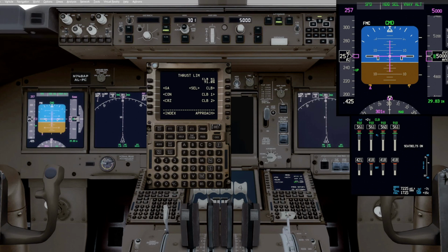And then, of course, when you bring the flaps out of up, normally we'll see go around displayed on the primary ICAS. If we had an engine failure, it would automatically go to continuous in most cases, but we could come here and select whatever reference thrust we want, and you can see it changing over here. So that completes the discussion on the thrust limits and the thrust limit page along with the takeoff reference page, and selecting assumed temperature versus fixed derate.